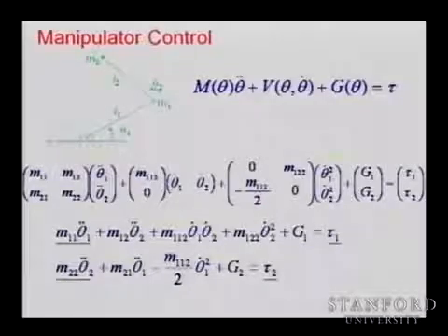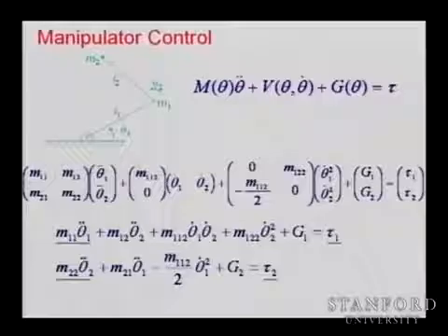So what do we see? We see here sort of mass acceleration, or inertia rotational acceleration, equal torque, but there are all these additional terms that are appearing. Essentially, the acceleration of joint 2 or link 2 is appearing in the first equation and is affecting the dynamic behavior of the first link.